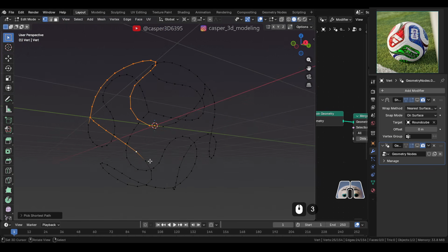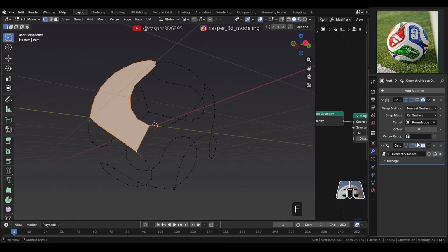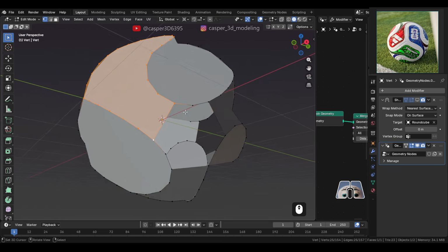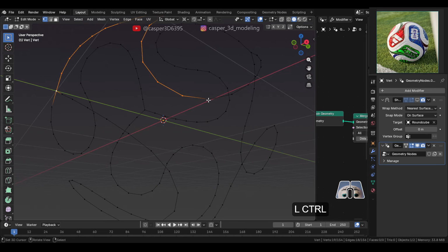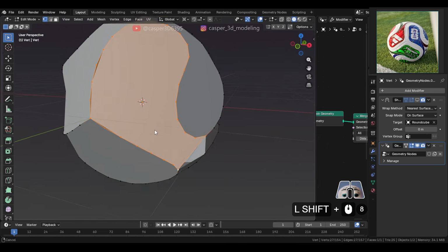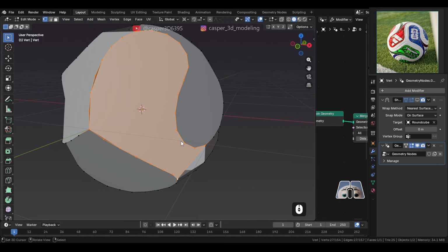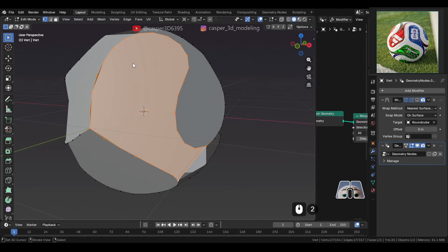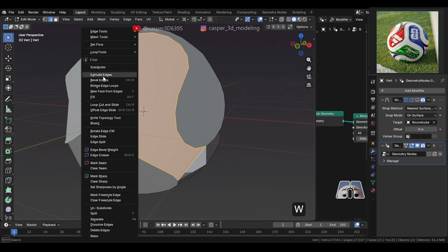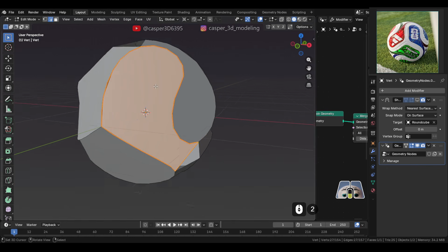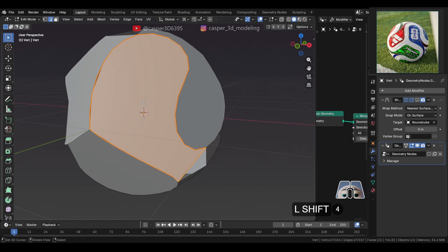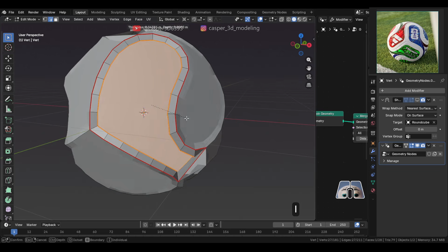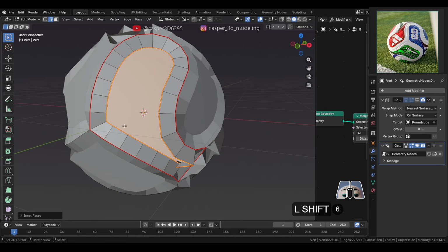So let's activate the geometry nodes modifier and see where the other section meets. The meeting point is right over here, so we'll only fill up to this point. Next, we need to build the geometry here with clean topology by connecting the edges. First, let's mark the border edges as a seam. This way, we can quickly select this section again later. Then inset this inward to protect the boundary structure.